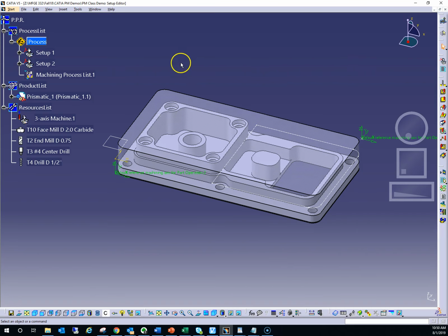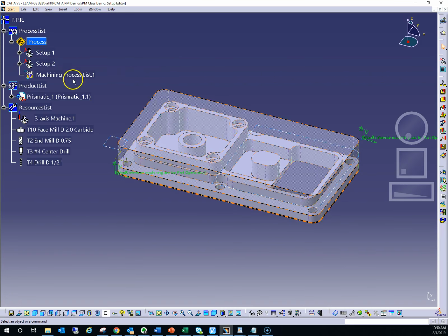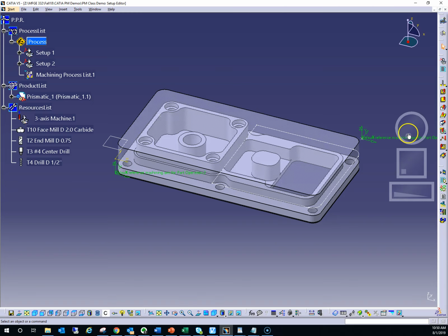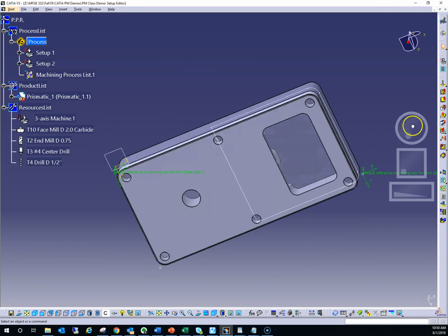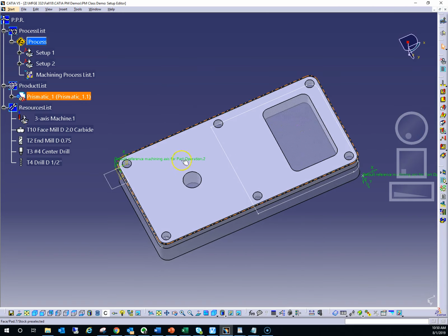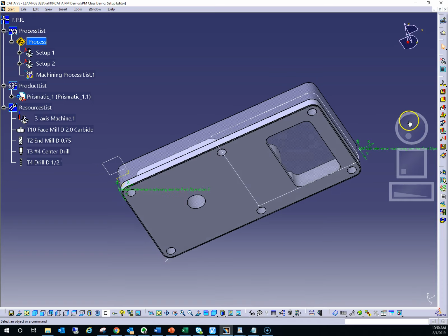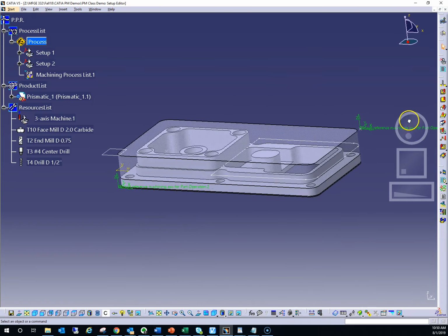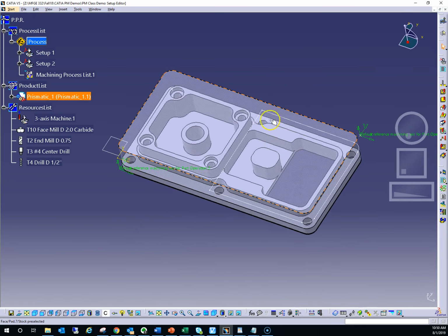If you've been following these videos, you would have completed all the machining for setup 1. This is the part here that we've been working with. Setup 1 is the underside of the part. If you recall, you did a facing operation, some engraving and chamfering. We now need to proceed to setup 2, which is basically to flip the part around and then to machine all the material away from the stock to leave the design that can be seen through the transparent stock.